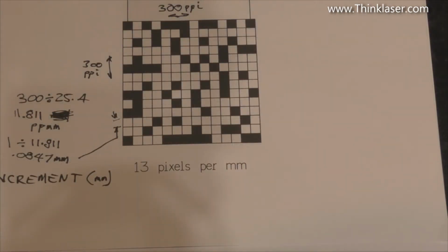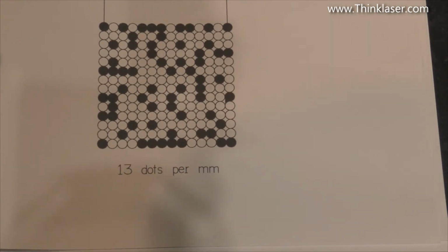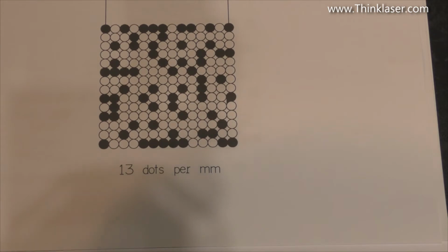Right, now the machine cannot produce square shapes. It doesn't work in pixels per inch. Although pixels per inch is the thing that drives the machine, what actually comes out of the nozzle are round dots. You've seen it for yourself. When you do a pulse burn down onto a piece of paper, if you set the focus right, you get a very, very fine dot. The machine works in dots per inch, and the resolution of the picture that you're trying to produce is in pixels per inch.